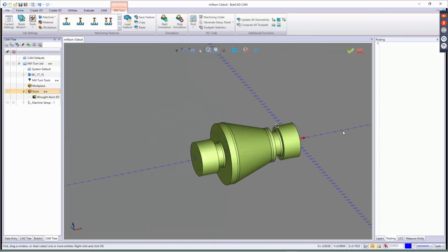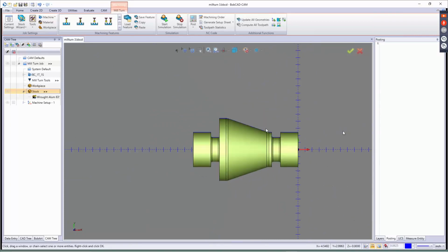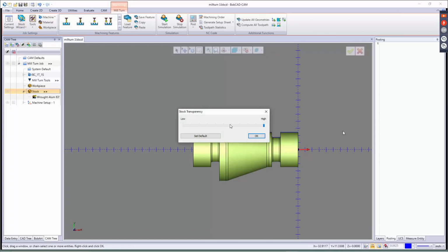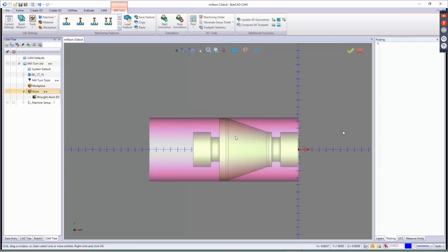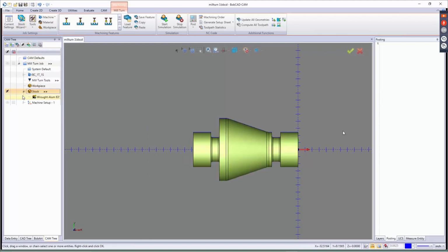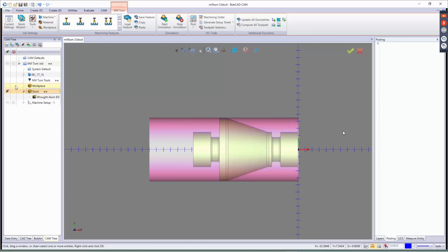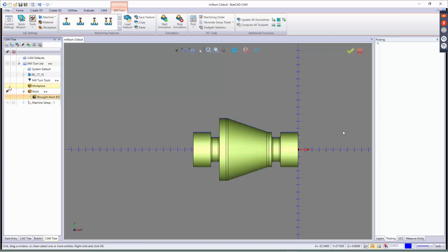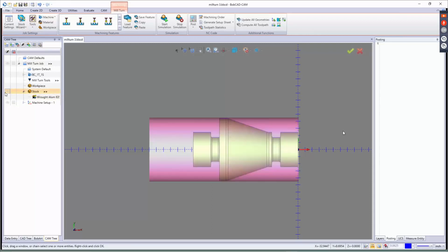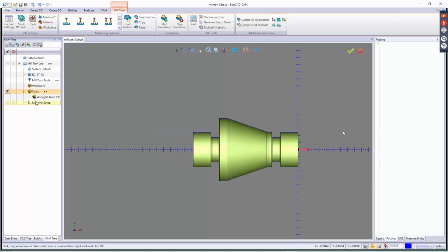It's there, but it's not there. I don't have to worry about it. I really don't need to see the stock if I don't need to on there. So I can come in here and I'm just going to come right about center here, save as default. There it is. What I usually do is blank unblank right there, and if I click on stock right here, it kind of appears. If I choose something else other than stock, it'll go away. So I can blank it out if I want to, and I usually do. I just blank it out right there.